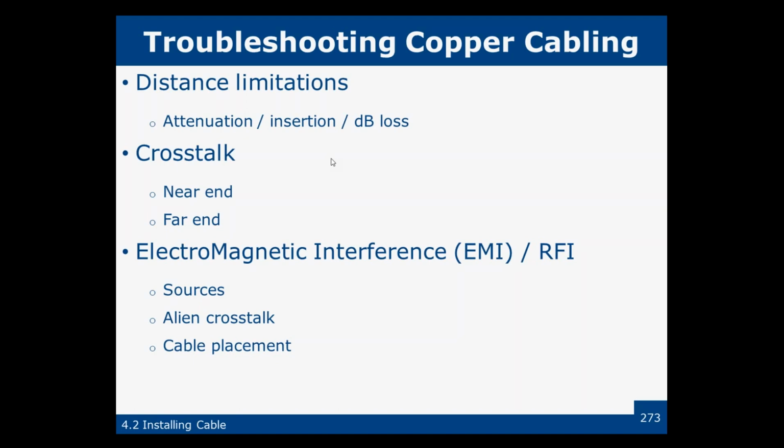In decibels, 3 dB is a 50% change, either up or down. What was their answer? Measure the insertion loss in dB using a cable tester. Although that's going to be a pretty fancy cable tester. Some of them won't measure dB. TDR might be overkill.